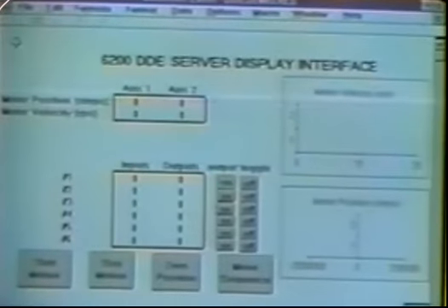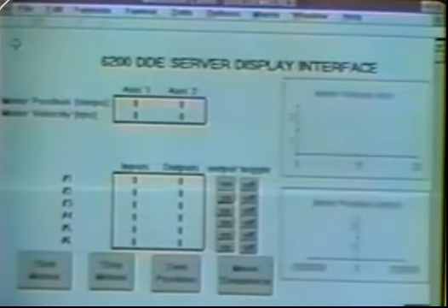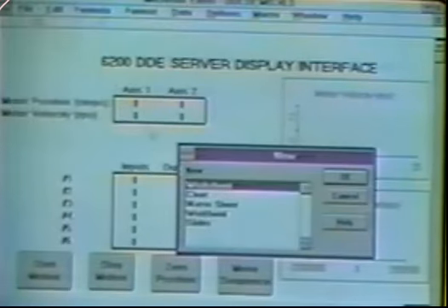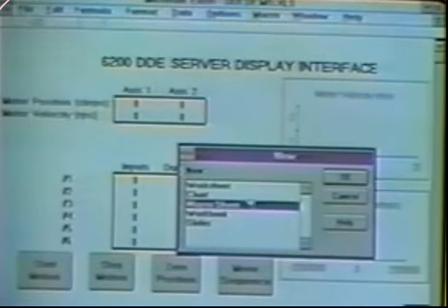We've now completed the remaining display cells using MV, IN, OUT, DDE request commands, and all the information is now displayed on our panel. We now must create the necessary macros and assign them to our buttons. We begin this by opening a new file and selecting the macro sheet option.